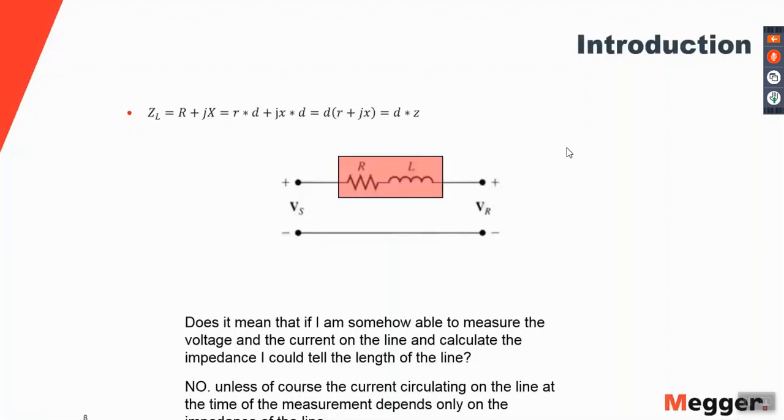But if you collapse that power, as it happens when you have a fault on the line, then you can say that if you're able to measure the voltages and currents at one point, then you can use the resulting calculation from those voltages and currents, which is the impedance, as the measure of the length of the line.